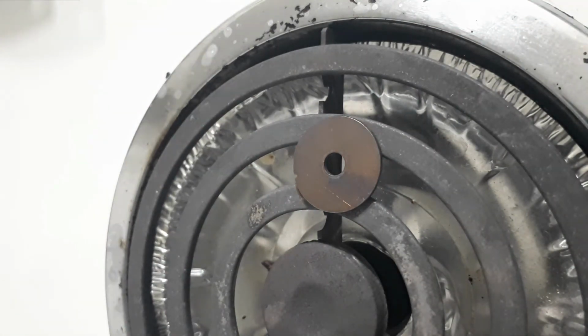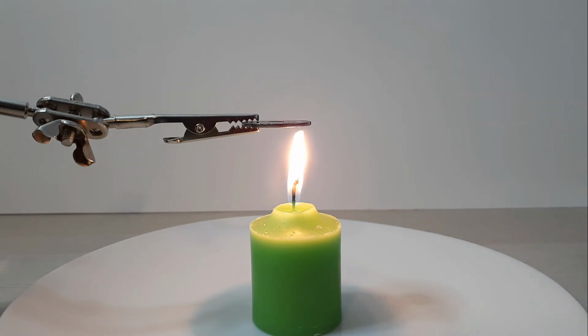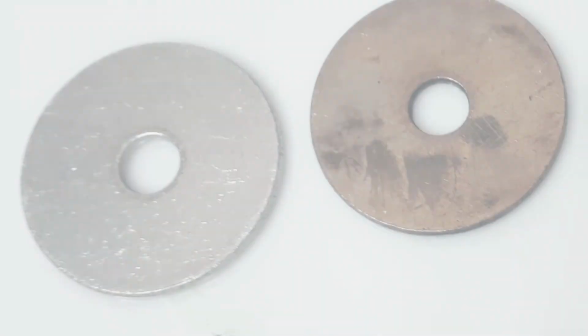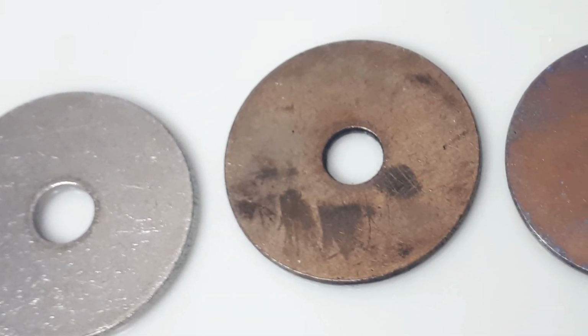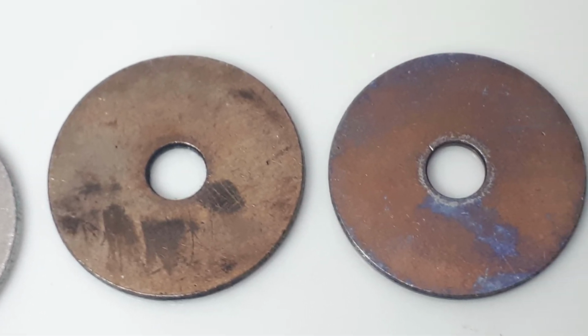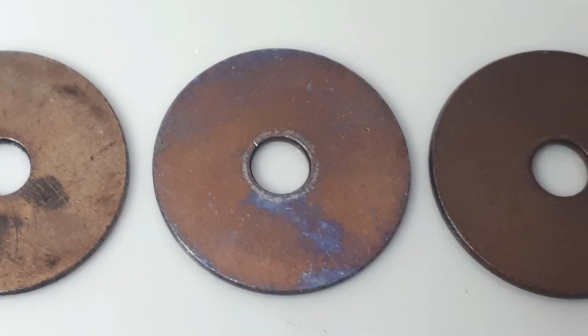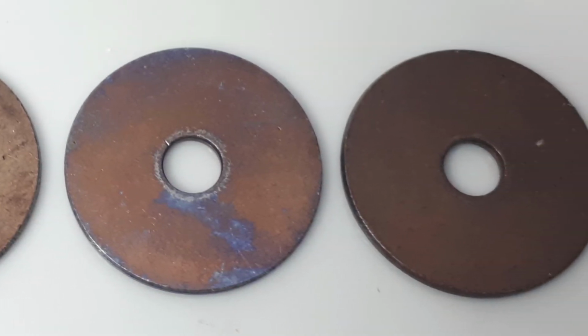As the name suggests, heat tint occurs when the surface of stainless steel changes color when heat is applied. More accurately, the oxide layer on the surface of the stainless steel thickens, promoted by the applied heat. Chromium is drawn to the surface of the metal, making it richer at the expense of the layers underneath, which could lead to inadequate corrosion protection in some applications.